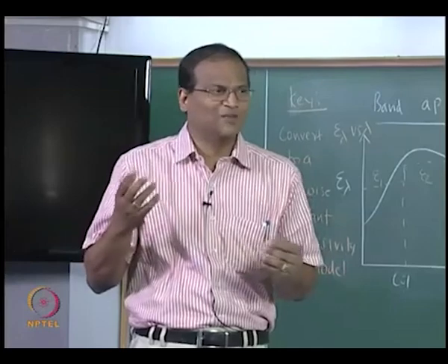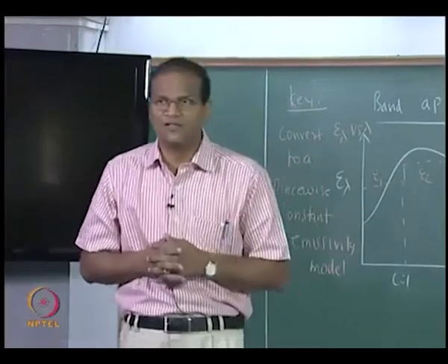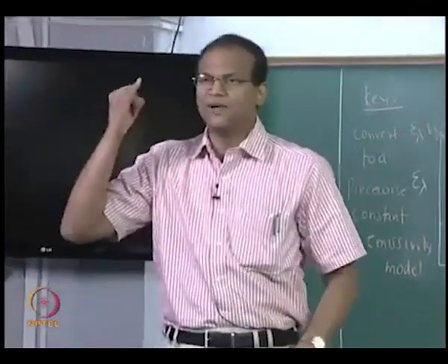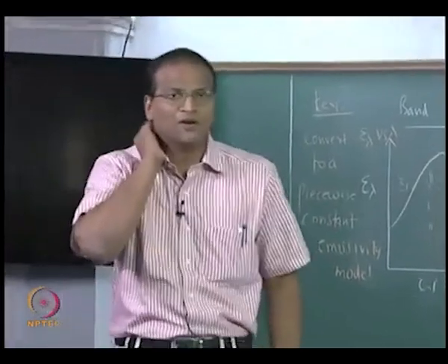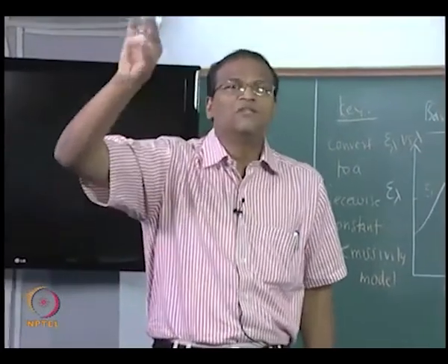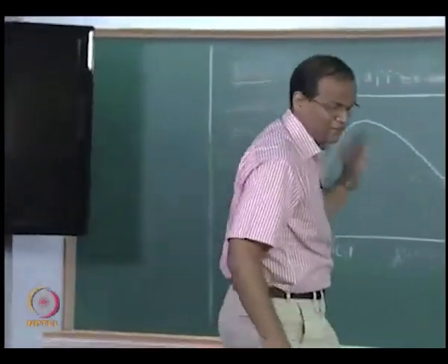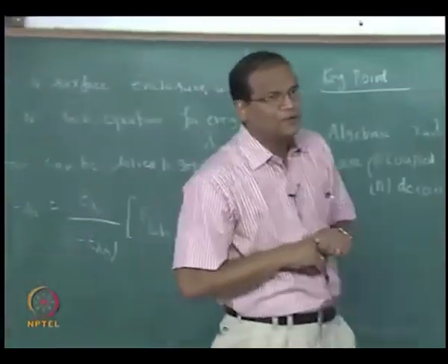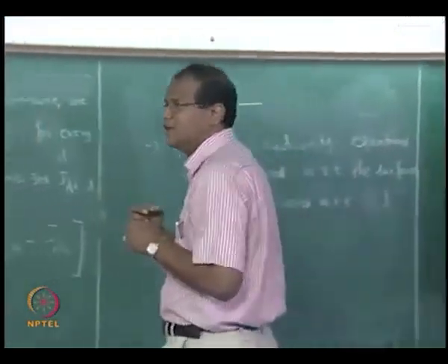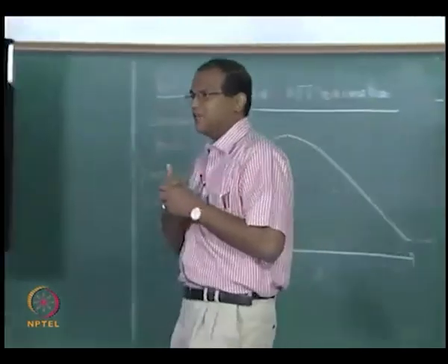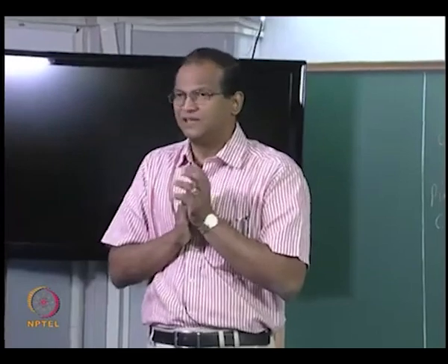Accuracy will also increase as we employ more bands, but it is a trade off between your computational cost and accuracy, right. So accuracy will increase with number of bands, complexity will also increase with number of bands. Accuracy is also critically dependent on how good this piecewise model approximates the non-gray body behavior. That is the final point which I have said is very, very important. Finally, the accuracy of the calculation depends on how good this piecewise constant emissivity model mimics the actual non-gray behavior of the surfaces under question.